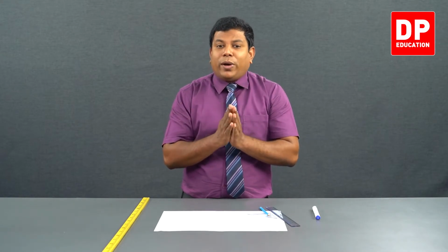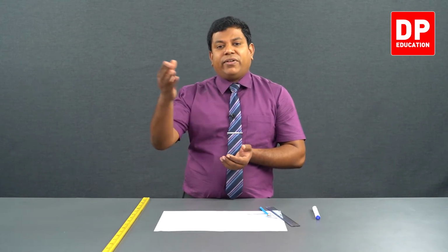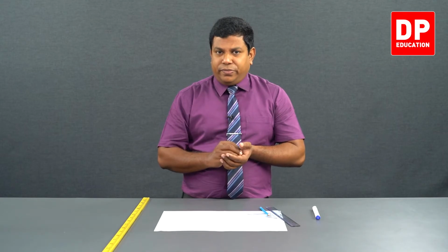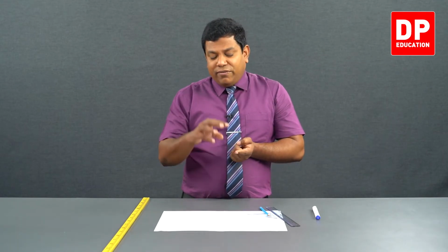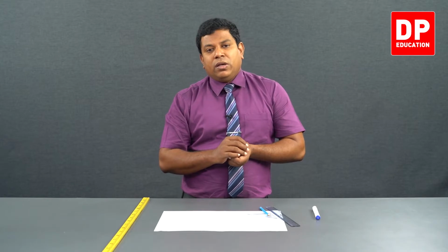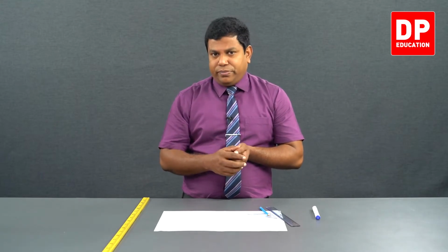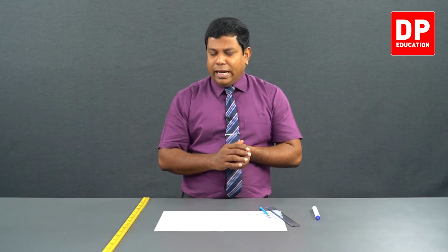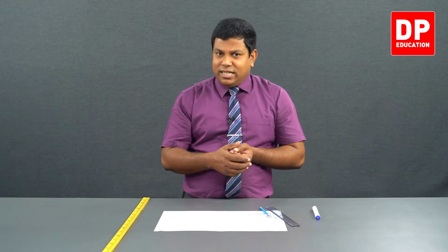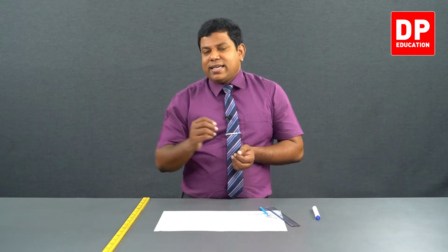Right? This is also a usual question in the exam. They ask you after the experiment, a student has got these values, which are slightly different from the actual values. What could be the reasons? There are multiple reasons for this. Reason number 1, we have taken an assumption that the pulleys that we used are frictionless and smooth. But actually you can't find pulleys with 100% friction free. There will be a little bit of friction, which we have neglected. If at all we can use some lubricants or some oil and improve the frictionlessness, but you can't make it 100% frictionless. So that's one reason why we may not get the exact answer.